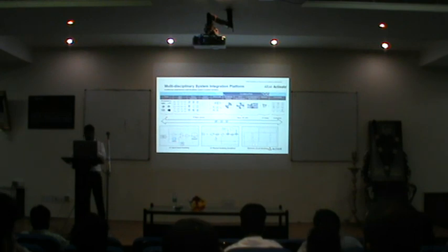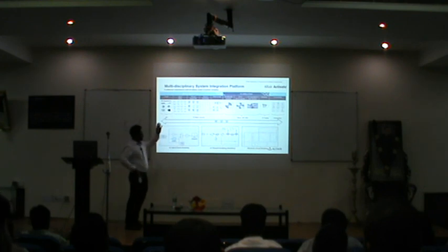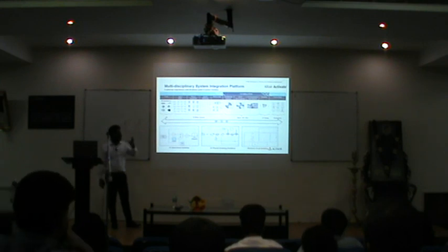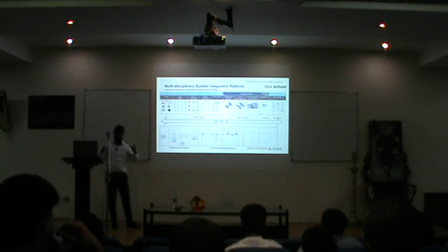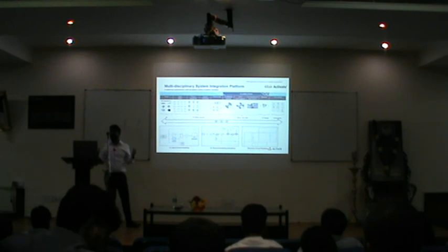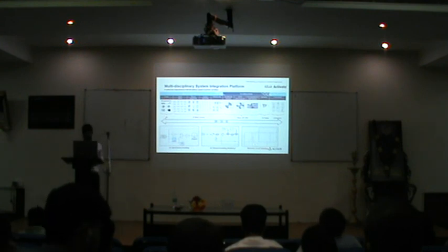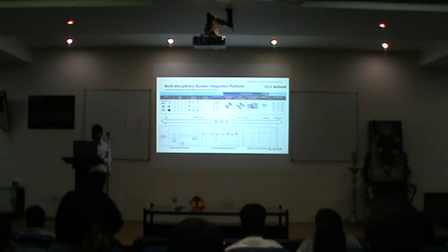So the latest version is 2023 and it is a platform for you to do scripting. You can do block level, physics-based modeling, specific to electrical, mechanical, thermal, hydraulics, pneumatics, multi-body, any specific domains you want to model and do the entire system level approach of simulating it, plus also doing 3D integrations as well. So when I talk about unique differences in 3D, whether you want to do molecular dynamics or electromagnetics or computational fluid dynamics, you can couple ACTIVATE with these tools.